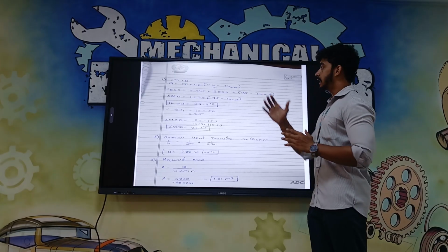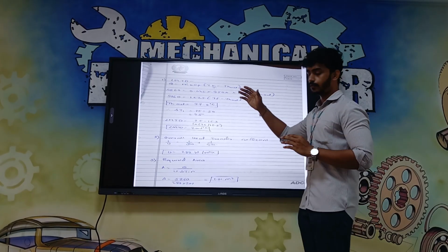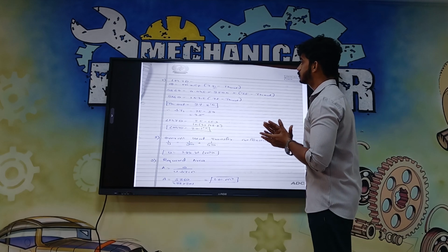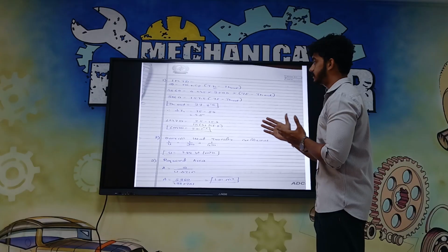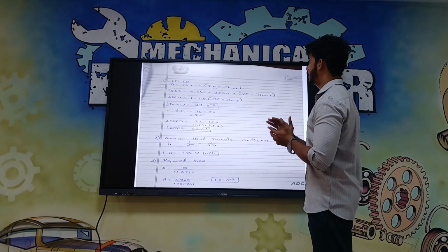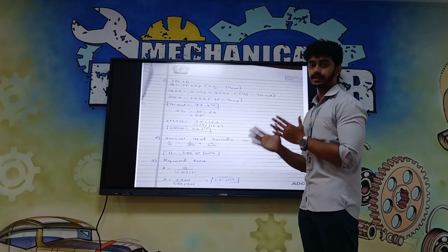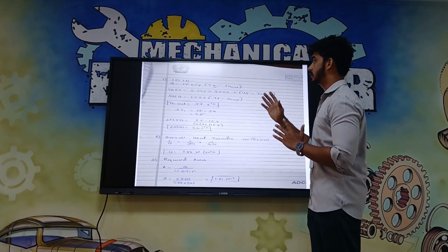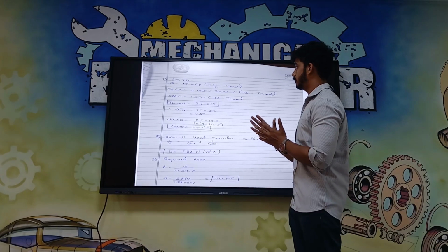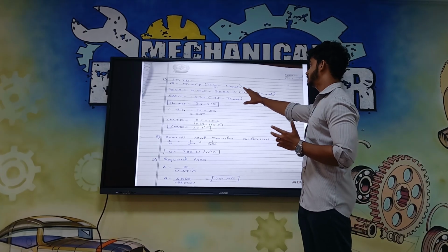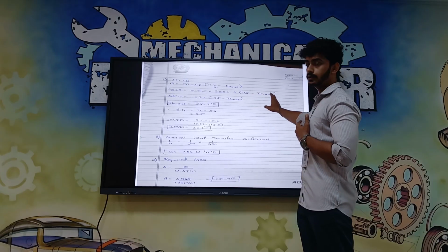Coming up next is LMTD. The formula is Q is equal to m_H into Cp into T_H in minus T_H out. We know Q is equal to 5860, m is 0.045, Cp is 3500, and T_H in is 75, and we have to find T out.